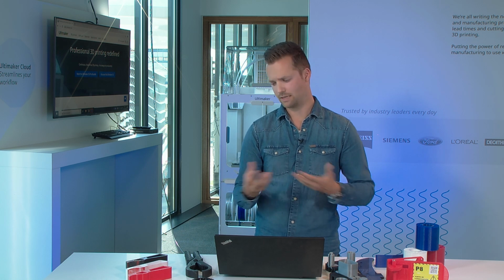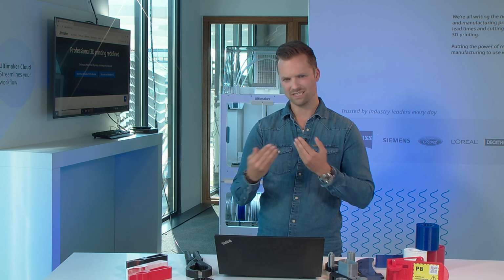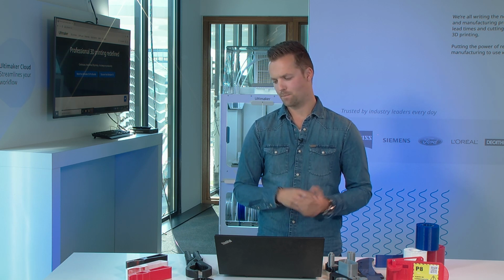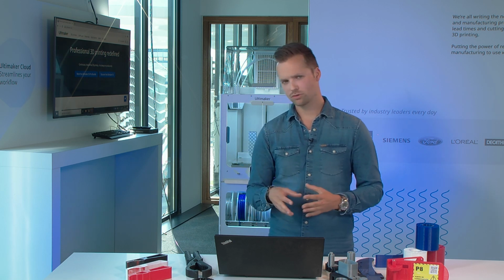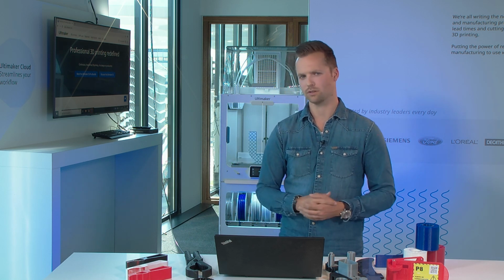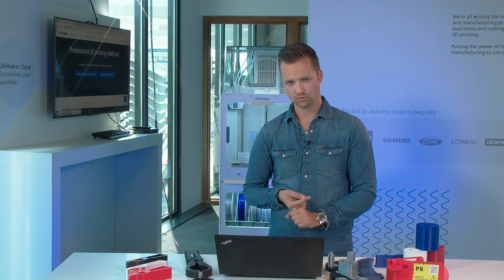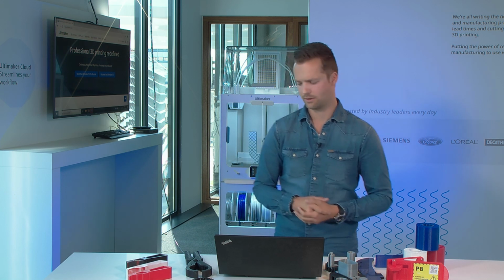At least it has to be in contrast with the other material, so you actually see something. When you do the outer wall extruder setting, it will be one wall. So depending on what kind of print core you're using, you can verify this. You can do it with a 0.4 nozzle core or a 0.8 nozzle core if you want to have a bigger outer layer as well.